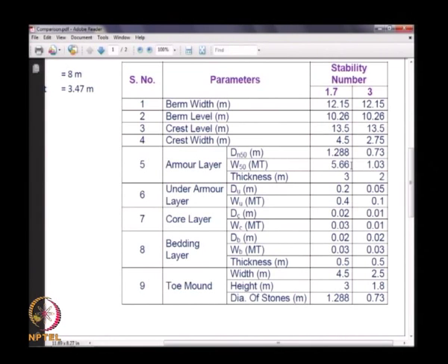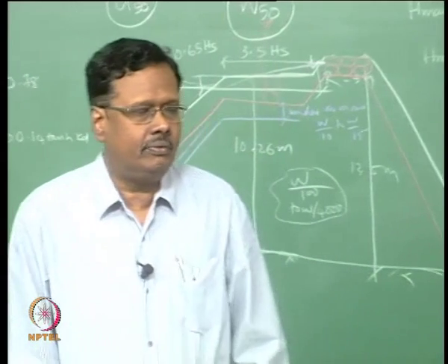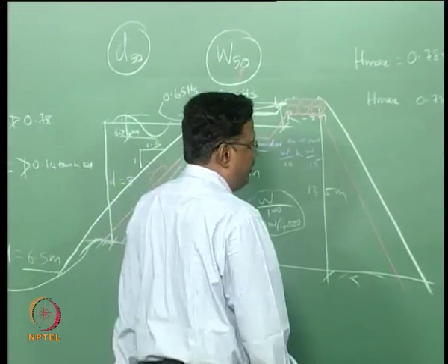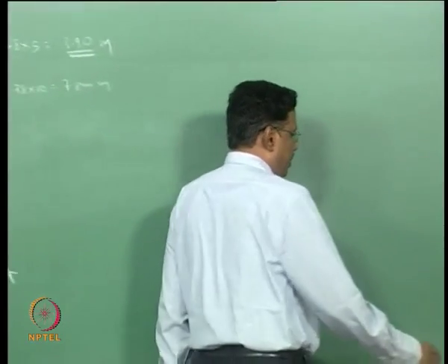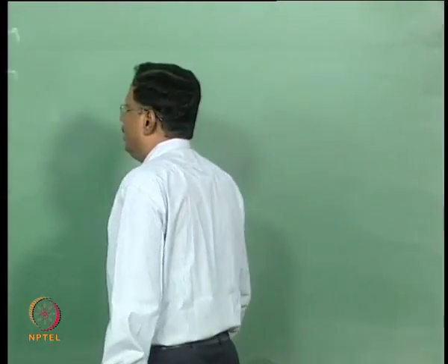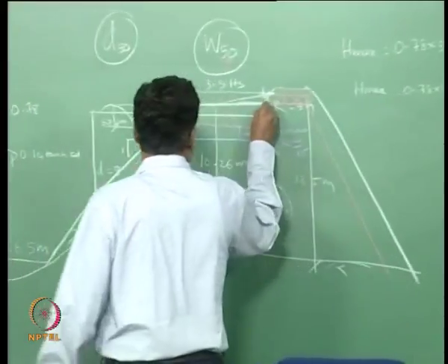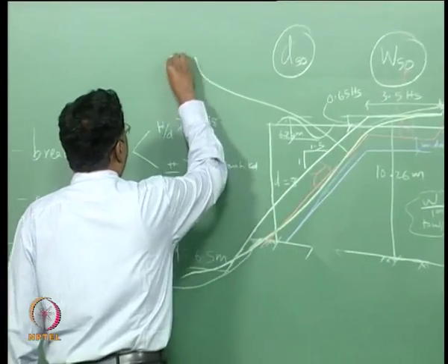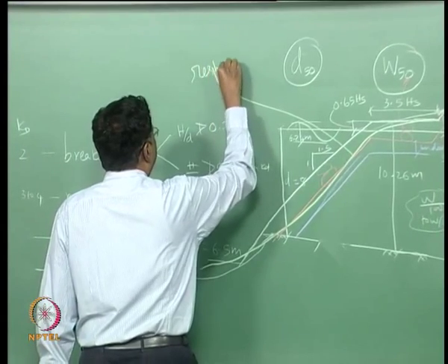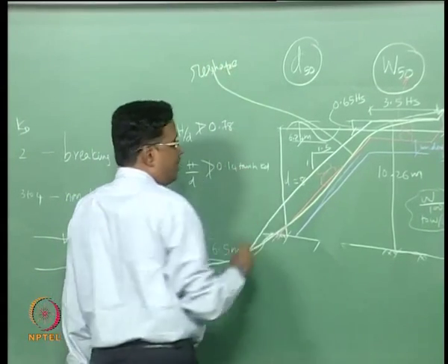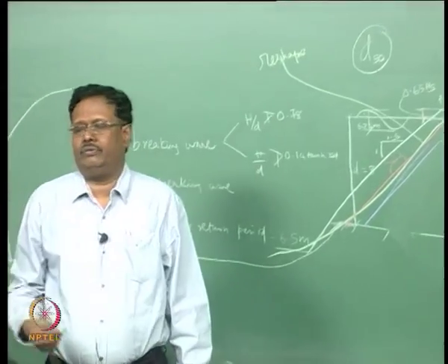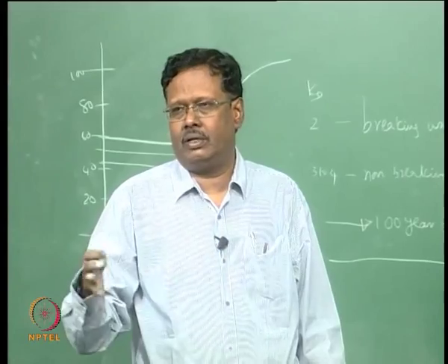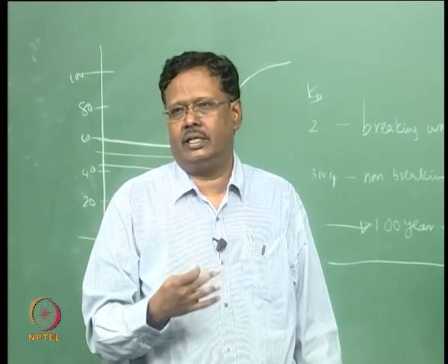See, there is a design philosophy. We allow the breakwater to take a shape, some kind of an S shape. So we allow this to reshape itself like this. It will take a shape. This reshaping is not done artificially by us. The waves which are attacking the breakwater will take the reshaping.